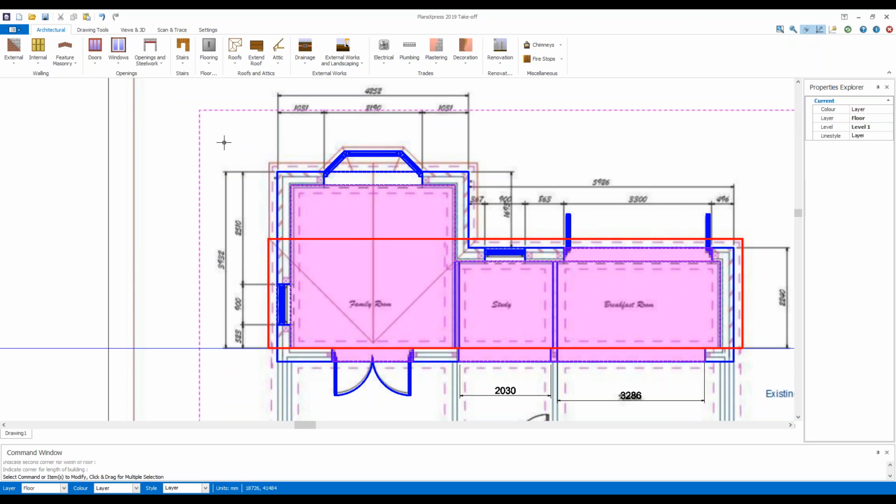That's a good question. Sorry for everyone else who hasn't heard it. Brickwork for the triangle underneath the roof. So I believe that's the gable end. That is automatically filled when you place a roof on. It's part of the wall, but it is automatically filled and is calculated. I will show you in a second.